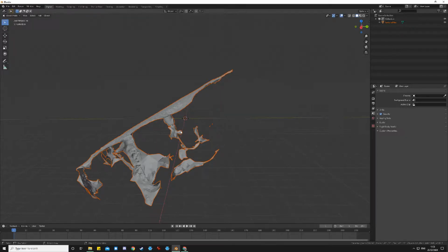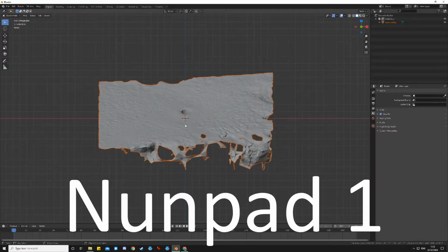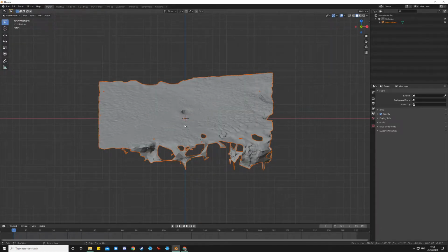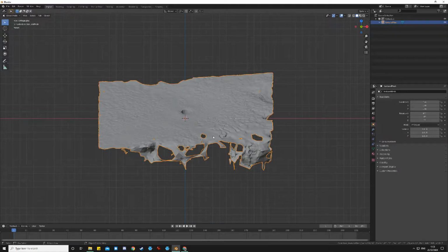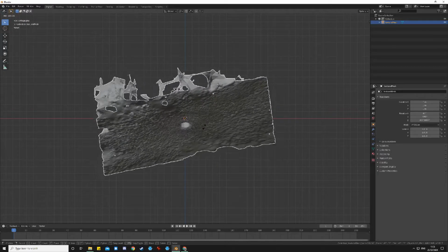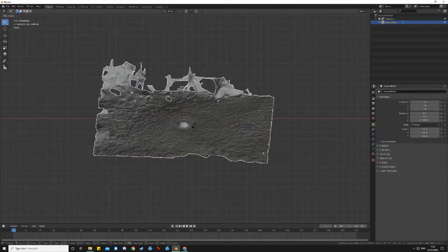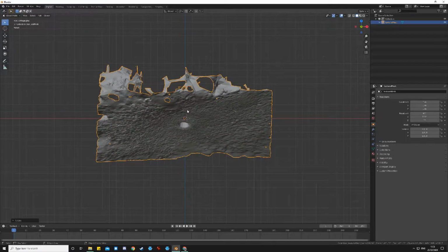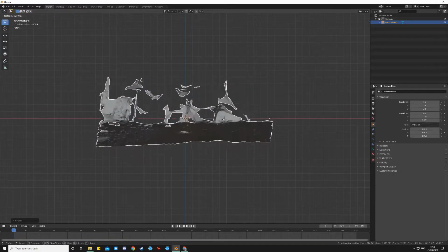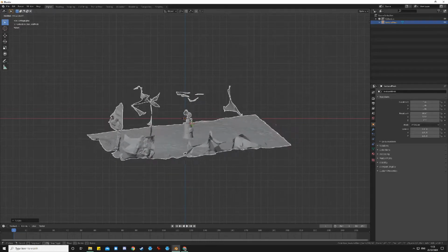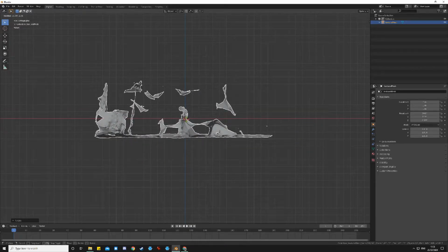So what I would do first of all is press number 1, which gives me an orthographic side-on view of where the bottom is. I'll click to select it. You see it's selected up here, and then I press R to start rotating it round, and then I press R when I'm happy which way it is. I'll turn it one way, and then I'll press it a second time because it gives me another type of rotation, which is a lot more like a tilt. That allows me to line it up with that red line. That's what I want to do.